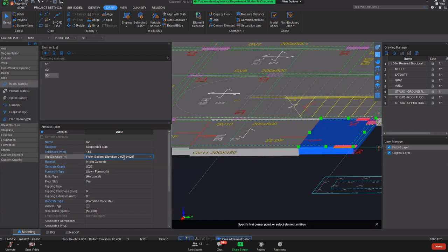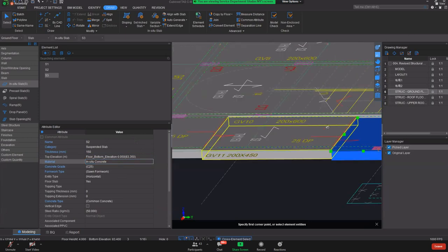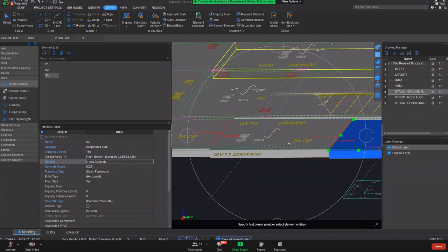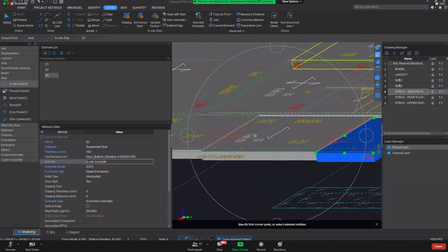If you only minus 1 time, okay, as you can see, I minus 1 time, it will still not have the drops yet. Okay, I need to minus 1 more time, 0.025, which equals minus 0.05. Okay, Chong got it right. So if you correct it, there you go. You have a 25 mm drop from the first panel to the second panel. Second panel, another further level down, 25 mm. Right? Able to get the drops?